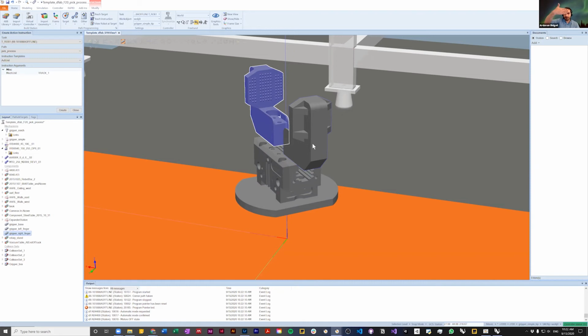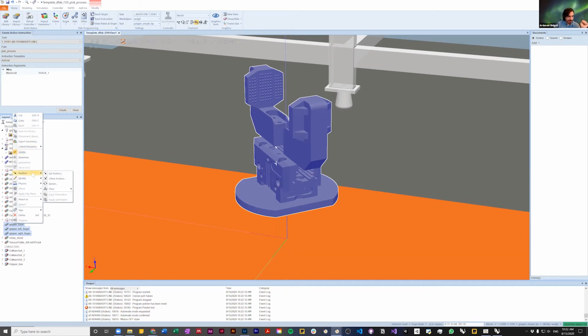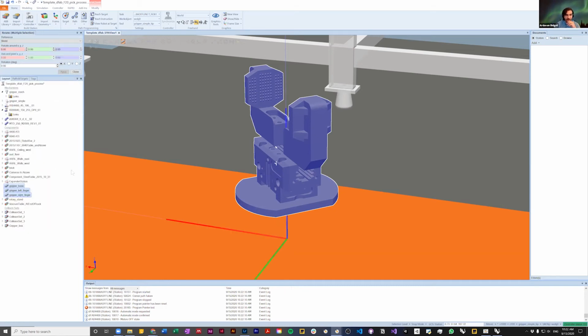They are 45-degree rotated. And this is going to make everything a little bit hard for us. So I'm going to select all of them. Remember, select all 3 of them, right click, and let's rotate them all together. And since they are located at the center of coordination system, it doesn't matter which coordination system we use. I'm using world.